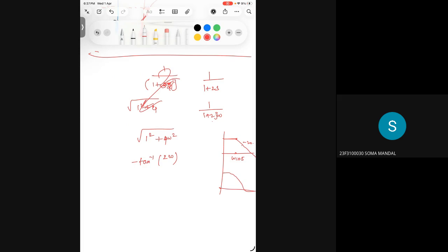Where do you find t? Here, omega equals 0.5, because it is 1 by 1 plus st, and t is equal to 2. So omega equals 1 by t, which is 0.5. We have to compare with the main equation, then we have to convert that. Find the magnitude and phase. From that, you will be able to draw this.